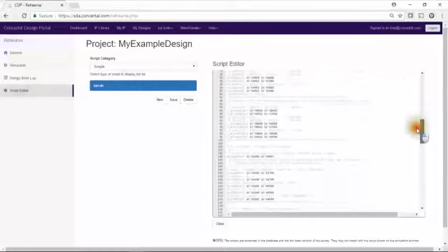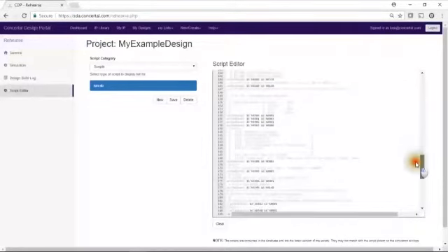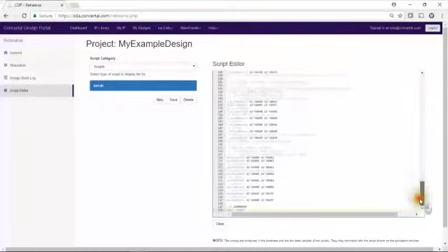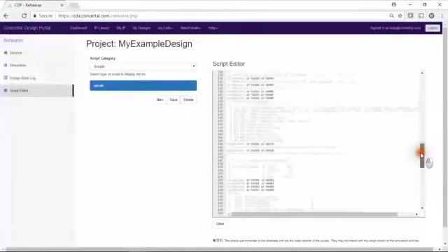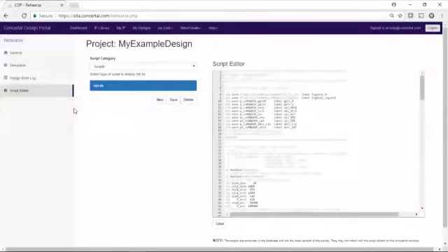The remainder of this script is simply setting configuration registers in the design and the test bench to specify stimulus, internal clocks and internal data routing, IP mode controls, and runtime controls. Once again, this particular compilation of the design was generated as a highly configurable design, so there's lots of control registers to set the chip up to operate as a system as we want to. All of these registers can be optimized in Orchestrate, and the design regenerated to only include the amount of flexibility that you really need to extend to an end user for your system.